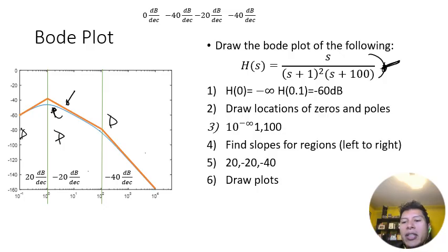And so if someone's like, I'm trying to design this circuit to work up to 20 kilohertz, and then they show you this, you're like, hey, my friend, this 100 should be closer to 20,000 because the response of this thing will be terrible at 20 kilohertz. But we need to develop this very quick way of viewing these responses so that we know how to modify the circuits without doing complicated math. That's the only reason why we're going over all of this. I hope this gives you an intuition of how to interpret.